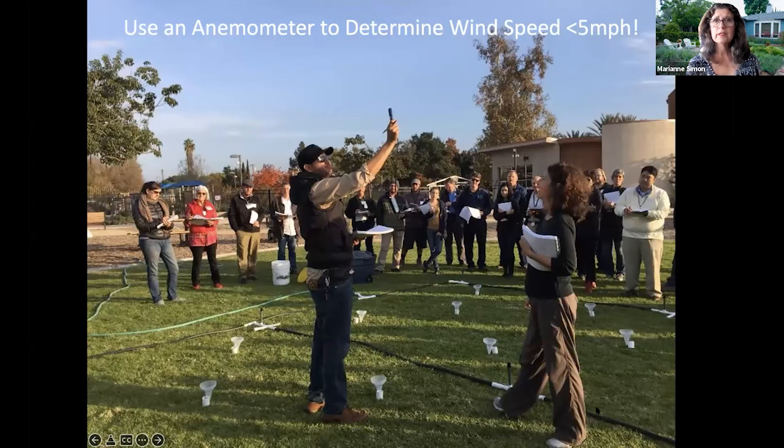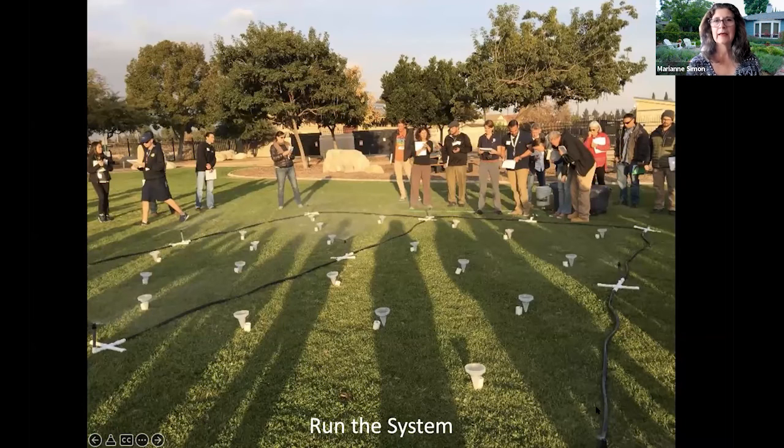Now, before you start, check those wind conditions, because if it's too windy, it will definitely distort the data. So the key number to remember is 5 miles per hour. There's this cool tool called an anemometer. You put it up in the sky, it whirls around and gives you the wind speed number. And then you run the system 10, 15, 20 minutes, depending on the type of sprinkler that you have. If it's conventional spray, it's running for a shorter period of time. If you're working with those rotary nozzles, you will be running it for longer. Rotors as well will run for a little bit longer.